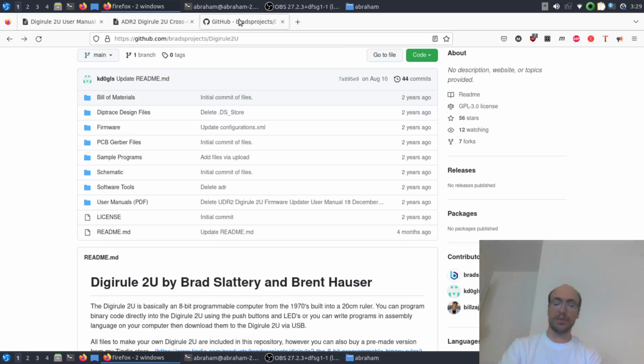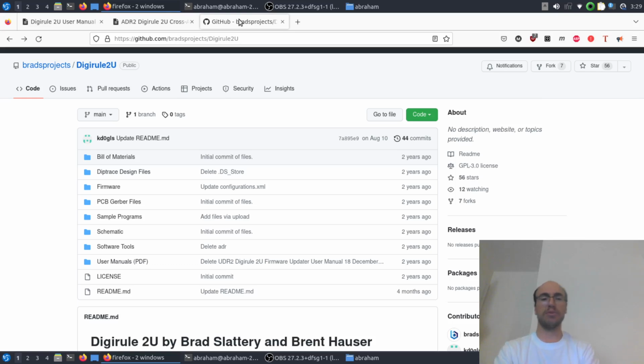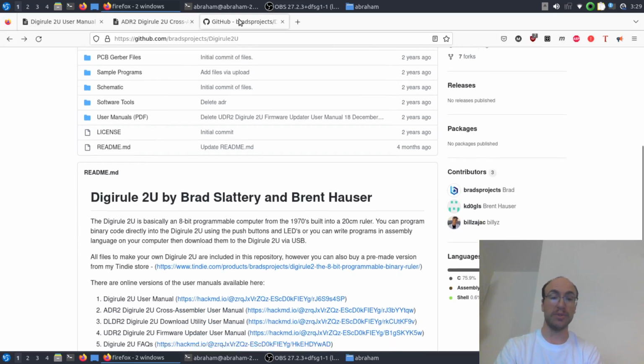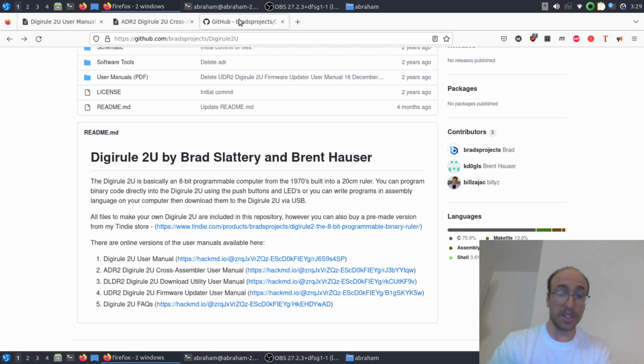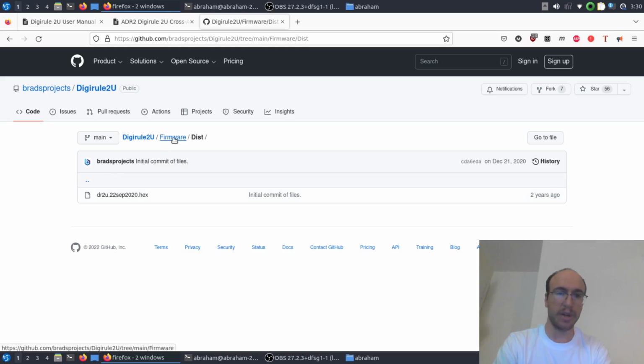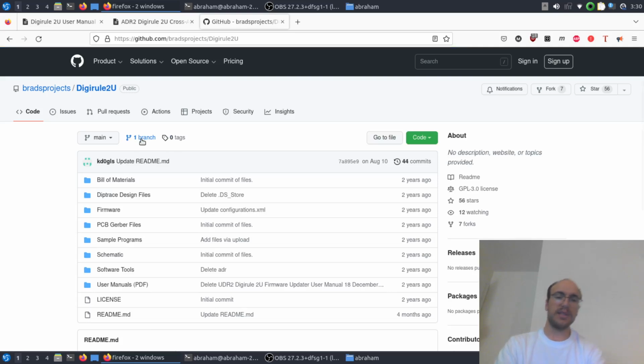The place to get all these programs is in the Brad's Projects Digirule 2U repository from Brad Slattery and Brent Hauser, who developed this fine device. What you want to do is clone this into whatever directory you want. I had this cloned into my home directory. It includes manuals for the Digirule 2U, the ADR2 cross assembler, the DLDR2 download utility, which I believe is just for Windows and Mac, not for Linux and Unix based systems, and then the UDR2 firmware updater, which I won't demonstrate since I just saw one firmware file present, and my Digirule 2U has that version firmware.